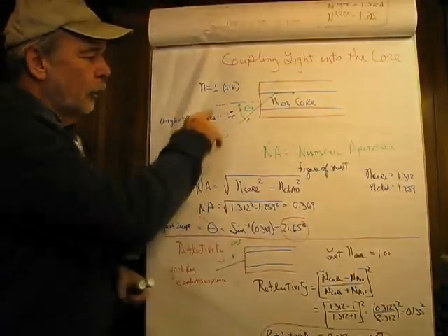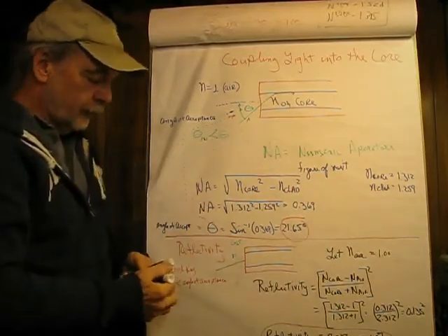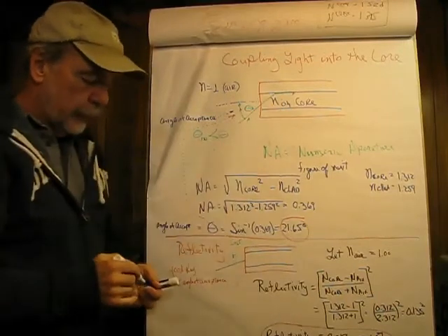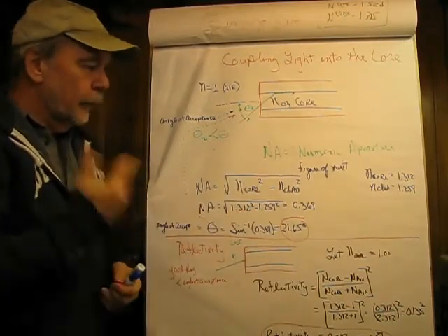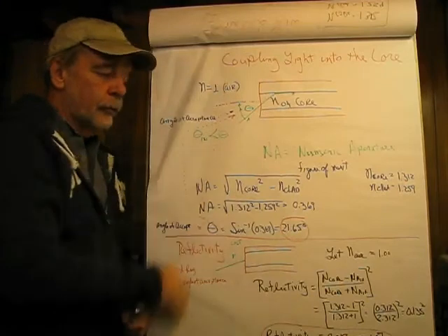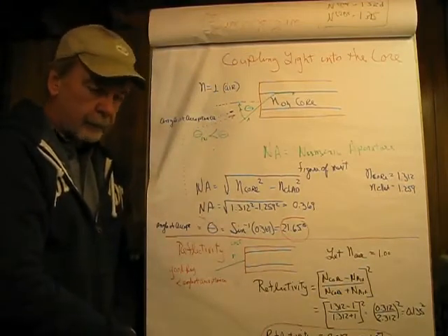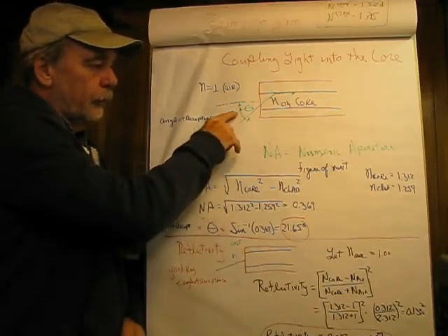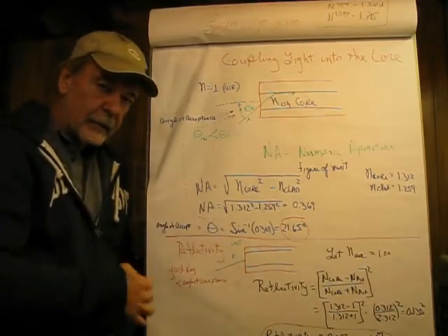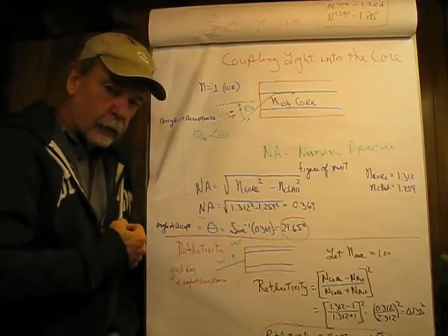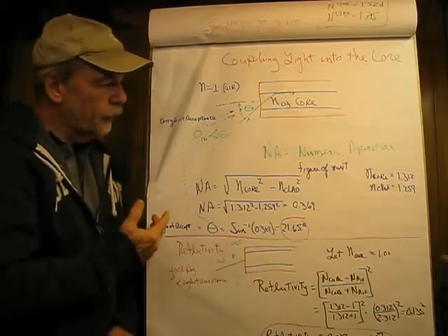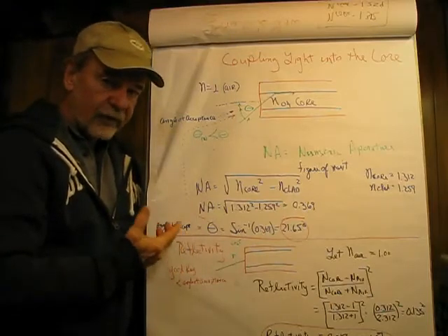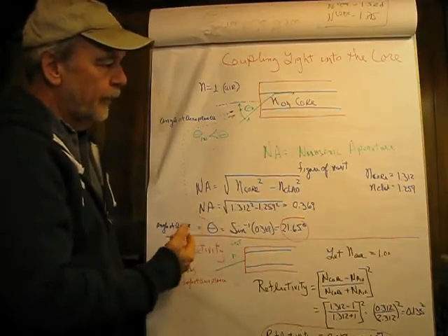So this will be the normal at the center of the axis, and I could put another normal right down here where this strikes the interface. Now here's the problem. We're launching this from, say, an LED, and we have many different rays, and we want to make sure that those rays meet the total internal reflection criteria for the angle inside the cable. So this is going to lead us into what's called a cone of acceptance. How do we find out what this is?